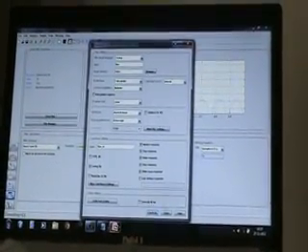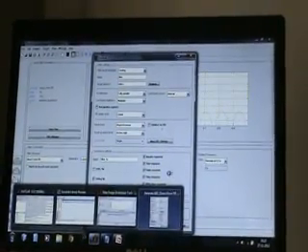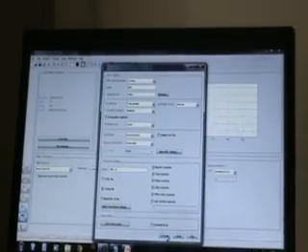After this generation process is done, in the command window of MATLAB, we get the modules of the filter as well as the test bench. This is the module of the filter which we have designed. This is the Verilog code which is completely given by the FDAtool. We can copy this into Xilinx and check out the power, area or delay of the filter which we have generated. And this is the test bench which is used to check whether the filter is working properly or not using some Verilog software like Xilinx.